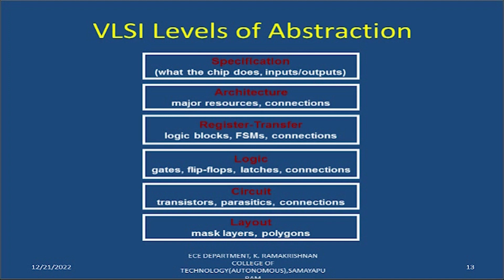And after converting that into a logic, we can convert and analyze it into transistor level logic. The transistor level logic will be analyzed by means of a circuit. In the circuit we can analyze its various parasitic elements and its associated transistors and interconnects. Then after that, that will be converted back into a final layout.